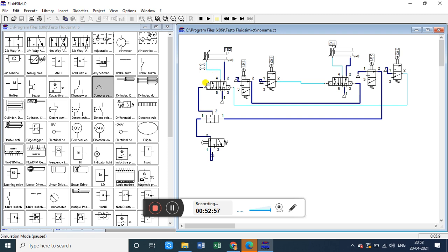Whenever this is applied on the left hand side, on the next click you will see this will shift to the right hand side. Yes, exactly. So the air will pass inside the cylinder from the left side line, and the air present on the right hand side will come out from the cylinder and be exhausted to the right side line.